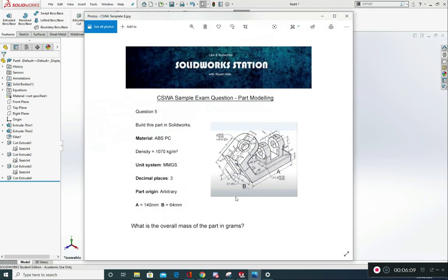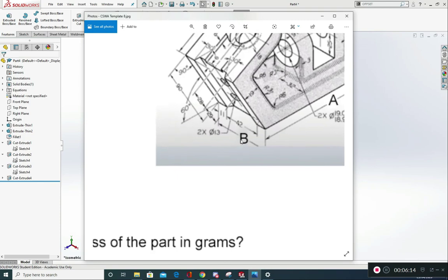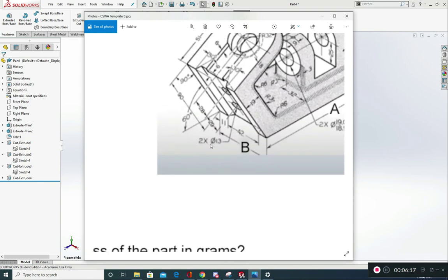Okay, we're going to look at now producing the two circles on the underside here. We know that these are 30mm for the diameter. We also know that the distance between each is 29, centre to centre, and 28 from this top edge to this centre. So from the top edge to the centre of circle 1, 28, then the centres are 29mm. So let's put those in.